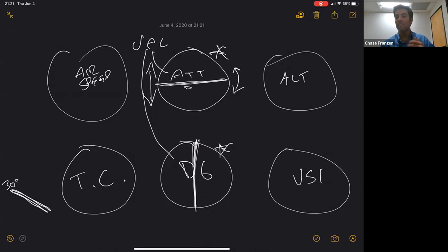But the instrument has a bit of a ratiometer inside of it that via, and this is where I'm going to explain this terribly because I've never been good at explaining the rate of turn indicator, but via a principle of gyroscopes called gyroscopic precession and rigidity in space together, the turn coordinator via that miniature airplane and these indications over here, when your airplane wing lines up with these indications, you know that your rate of turn is a perfect 3 degrees per second. Regardless of bank angle, regardless of speed that you're going through the air, your turn coordinator indicates via that spinning gyro that's electronically driven that the rate of your turn is 3 degrees per second or 2 minutes all the way around.